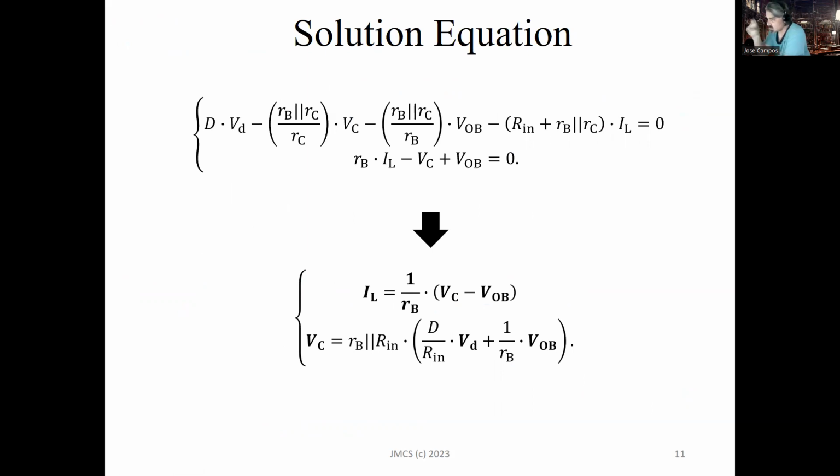So with this information, now we are able to calculate the capacitor and inductor regarding the ripple max percentage that the problem gives. I mean, in this problem, it's supposed that the problem gives us the max ripple available for the inductor current and the capacitor.